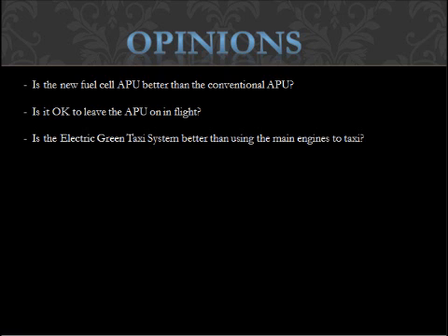The fuel cell auxiliary power unit is 75% efficient in converting jet fuel into electrical power during cruise. Thus it is a money maker when it comes to long cruise flights, as it saves a lot of fuel. Finally, in the future, fuel cell auxiliary power units can power airplanes' cabin pressurization, environmental control system, lighting, cockpit instrumentation, wing anti-icing protection, and control surface and landing gear actuation, which frees up all engines and allows them to devote all the power to thrusting the airplane, which is an admirable advantage.